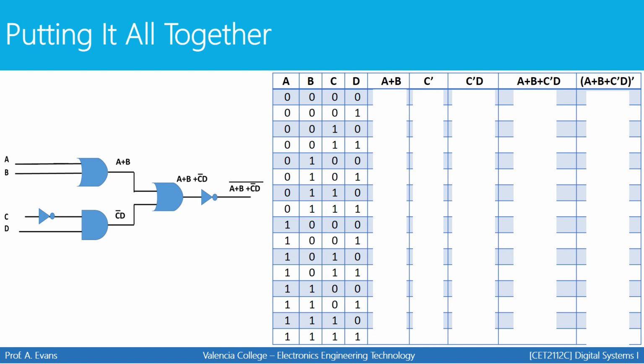Next, here's the truth table. You have 4 inputs, so again, you're going to set it up the same way that we did in the first example using truth tables. Make sure that you follow the pattern that was described. This will never change. If you have 4 inputs, your input section should always follow this pattern no matter what. It's the output that'll change depending on what the circuit is supposed to do.